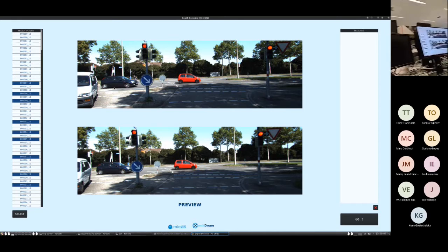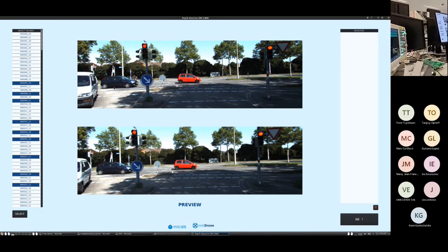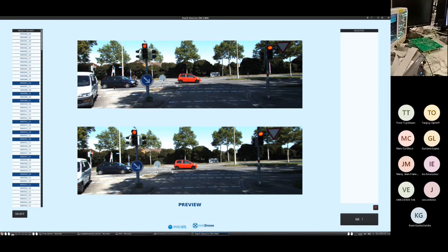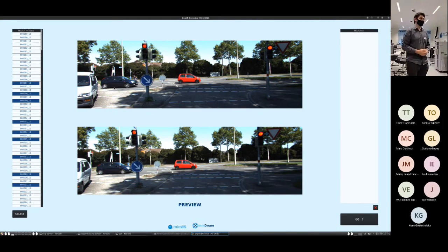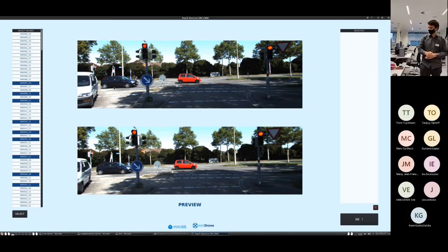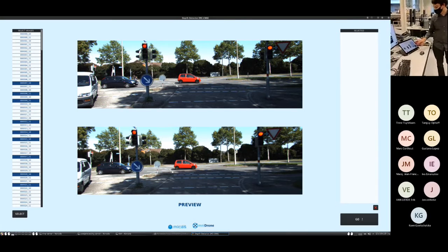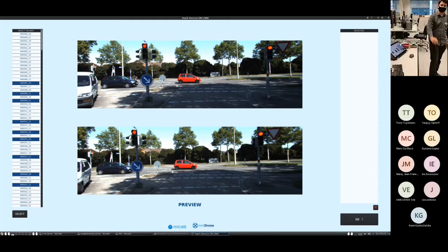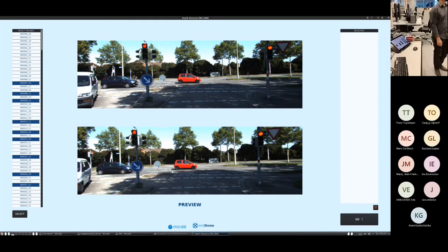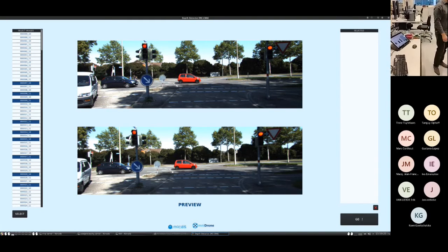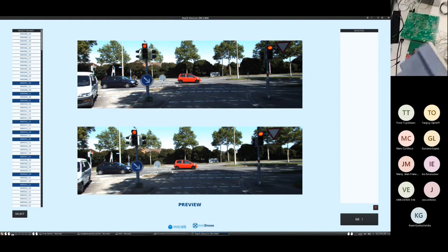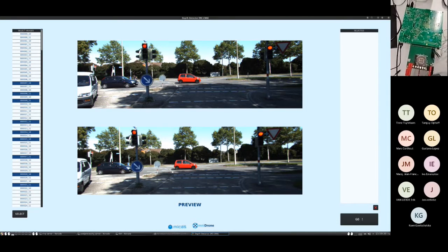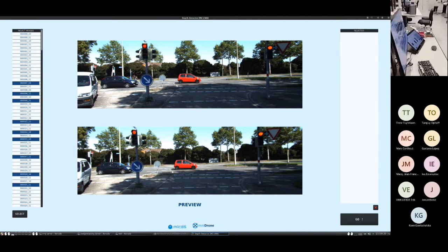The application is just as a proof of concept, mostly for this depth first processing, showing that we can do it with this amount of bandwidth, and then we can process neural networks without the intermediate data. And while this network is only 4 layers deep, we're at the moment only using 20% of our on-chip feature memory. So make it 5 times deeper, and we still wouldn't have any more I/O externally. Then we would be saving quite a lot more of the I/O and quite a lot more of the energy as well. And so yeah, it's more like something for that.